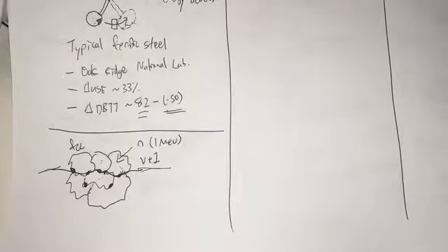FCC is maybe more naturally resistant, because the grains themselves do not exhibit the transition. It's just that between the grains voids form, and as a whole the material becomes more and more brittle. That's one way of thinking about it.